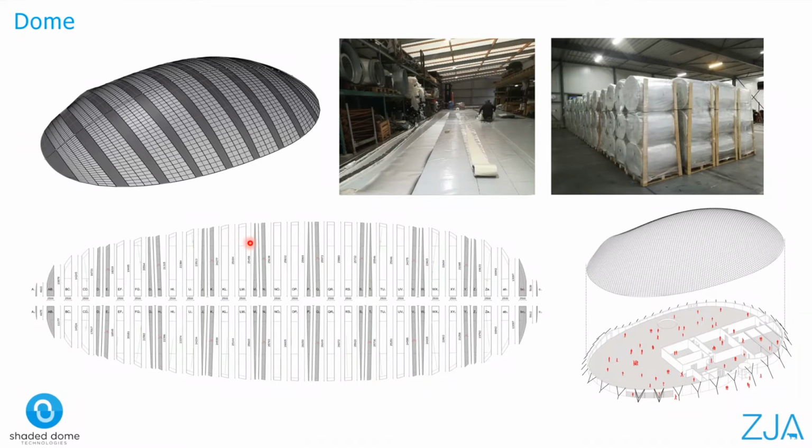exterior fabric. The strategy was to make as many straight strips as possible and few wedges to create the necessary curvature. The sizes of the strips were also determined by the rolls of fabric that were available at the production facility of Poly-Ned. We tried to optimize the shape to get away with doubly curvature occurrences and approximate the 3D model as close as possible. In this entire process, it was important to be very accurate, consistent, and take tolerances into account.